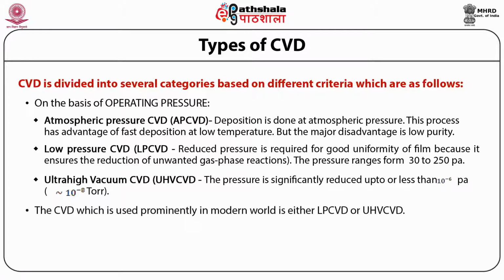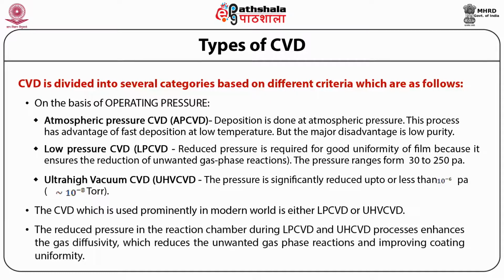The CVD which is used prominently in the modern world is either LPCVD or UHV CVD. The reduced pressure in the reaction chamber during LPCVD and UHV CVD enhances the gas diffusivity, which reduces the unwanted gas phase reactions and improves coating uniformity.